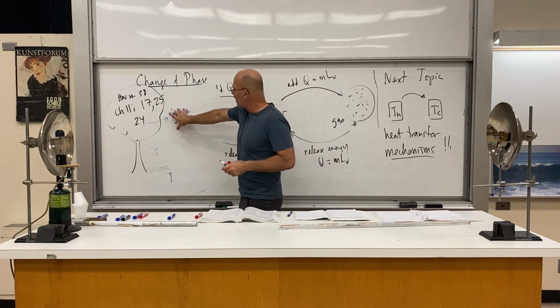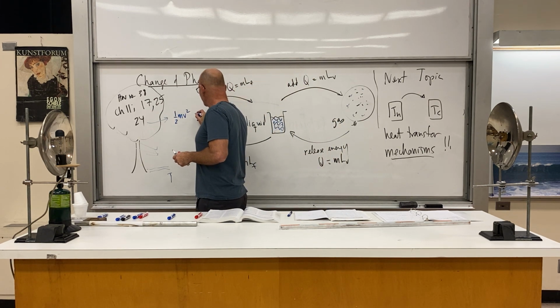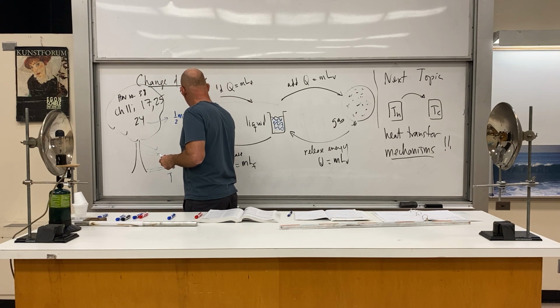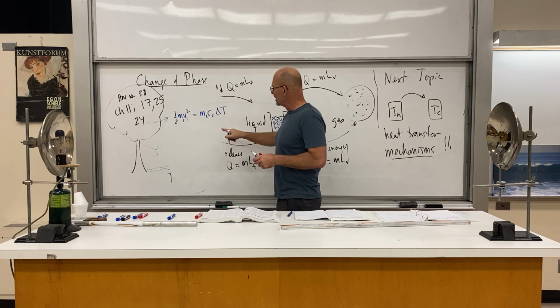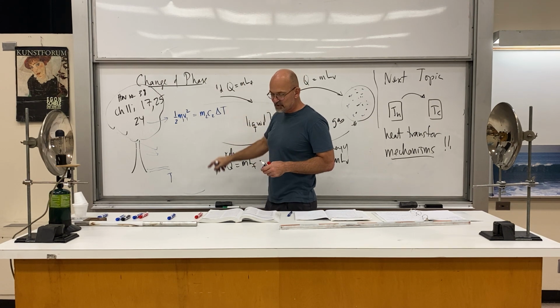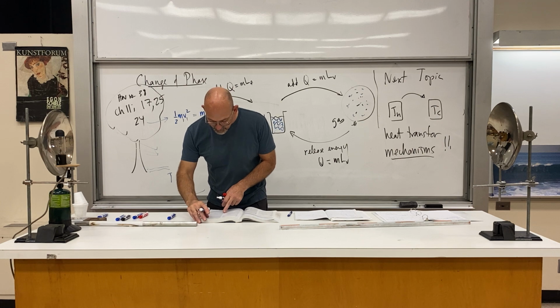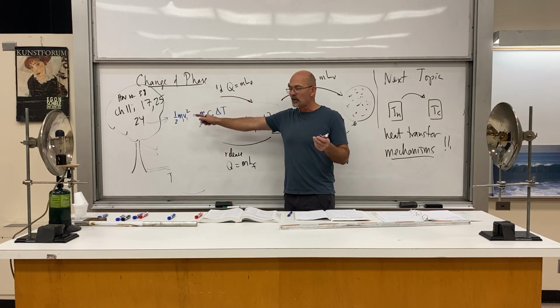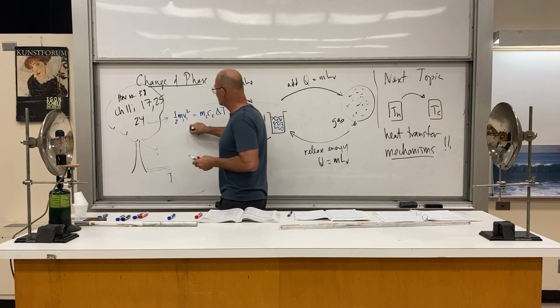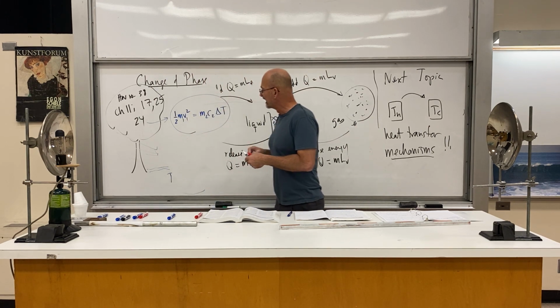Okay, but this is the car, half m1 v1 squared, and that's going to be equal to m2 c2 delta T, where that's the change in temperature of your brakes. So you have to monkey around with the, yeah, they give you all, there's 4 brakes, you have to add all the 4 masses. So yeah, it's an interesting problem there too. And let's leave it at that.